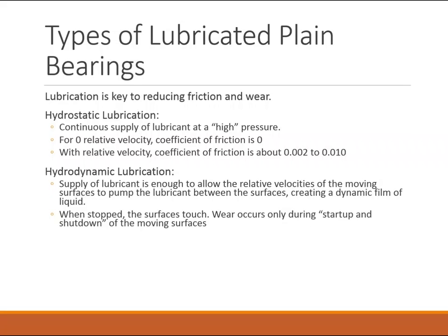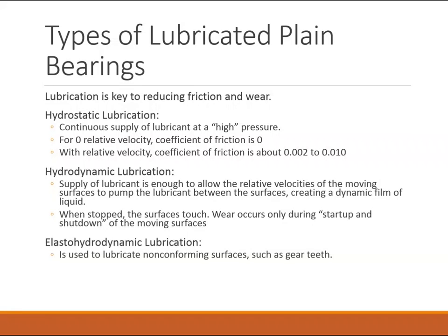This means when everything is stopped, wear could occur. So wear only occurs during startup and shutdown. This is why you do eventually have wear in a car engine, for instance. Everything is perfectly fine as long as the car is running, but during startup and shutdown, you might be tearing up your journal just a little bit.